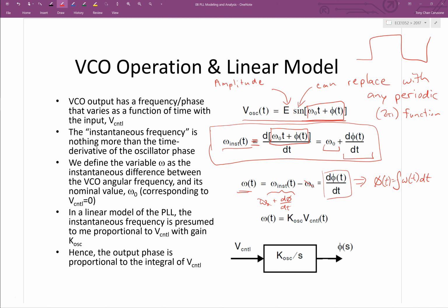If the symbolic derivation here is not providing any intuition, another way to think of it is that we can arbitrarily define the nominal frequency omega naught of the oscillator. It makes sense to pick it to be the actual frequency that's somewhere around where we expect it to oscillate. But in fact, mathematically, it's kind of arbitrary how we choose it. So let's say that we're expecting this oscillator to run at 1 gigahertz, but in fact, what we observe is that the phase is sliding a little bit to the right every time. Every clock cycle, it goes a little bit to the right.